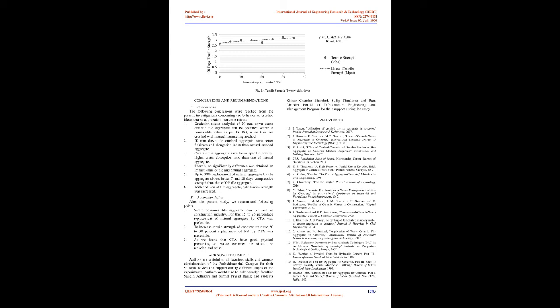Density of concrete. This test is performed to measure the density of the concrete. Cubes of 150 mm size were used for the purpose of the test. Densities of cubes were measured at 7 and 28 days. The steps followed while performing the test are as follows: density of concrete equals W by V, equation 3.